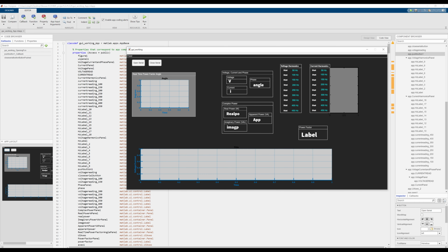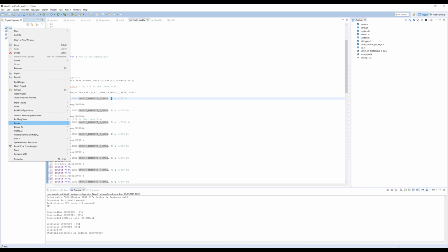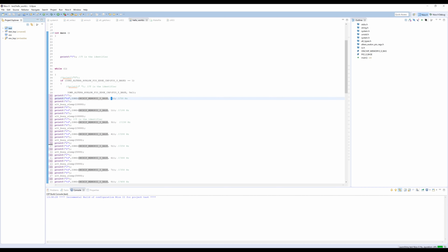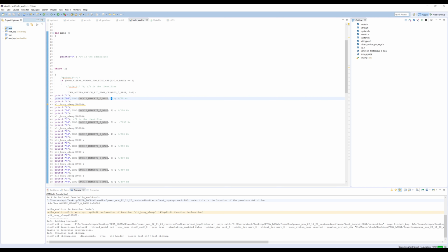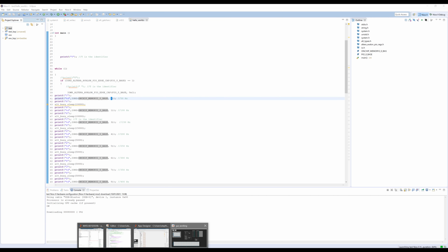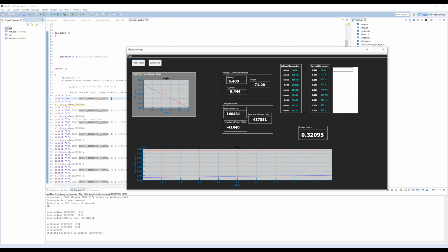Now, one thing I have to remember to do to make this work is, first of all, make sure the device is programmed, so the SOF file has been sent. And then I just have to make sure the code here is running on the embedded processor. Yep, I just made some cosmetic changes to that code previously. That should be up and running, and then we can open serial, and you can see we've got something.